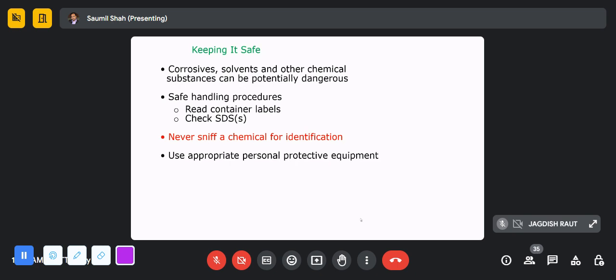Otherwise, if you do not do periodic maintenance of that particular line or wall or equipment, then that chemical can corrode your equipment and it can lead to some big disaster, or leakage over a period of time, which comes out to the atmosphere directly from the leaking point and creates more hazard at the workplace. So you need to review the SDS for that particular chemical and review your maintenance procedure, material of construction, thickness measurement, everything, in a repeated manner at every fixed interval.